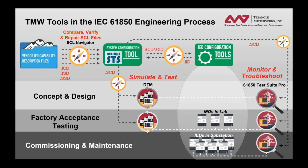Okay, I've got a specific question here on a use case, and basically they're asking if DTM can be used for this purpose. I'm looking to upgrade a currently serviced substation, which is using 61850 GOOSE messaging for the substation interlocking. As I will be upgrading IEDs on a bay-by-bay basis, I will need to simulate GOOSE to support the existing interlocking system and maintain the GOOSE quality bit as each bay is upgraded. Can I use DTM for this? Yeah, absolutely. That seems like a really good use case for both DTM and TSP. That's one of the things it's designed for, upgrading old substations to newer equipment. So absolutely.